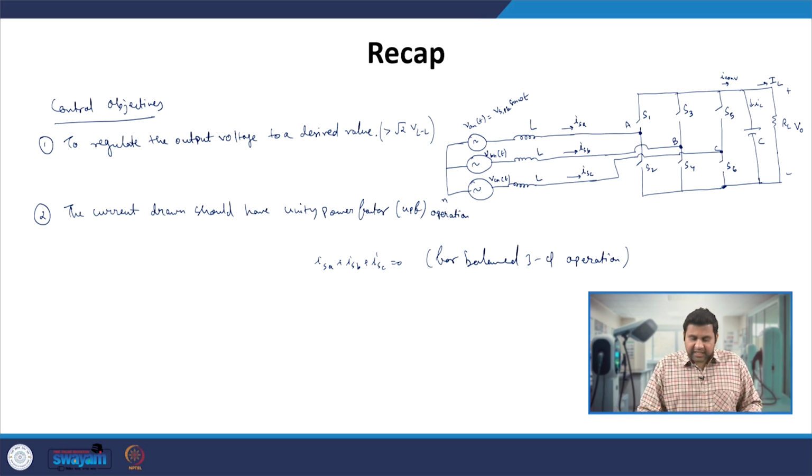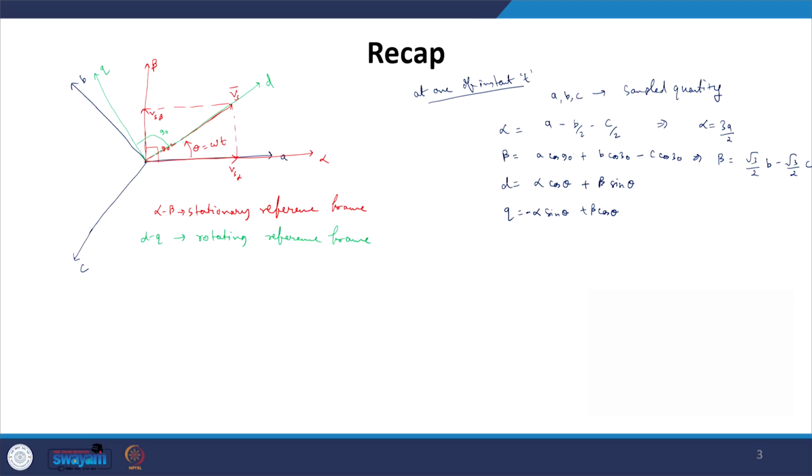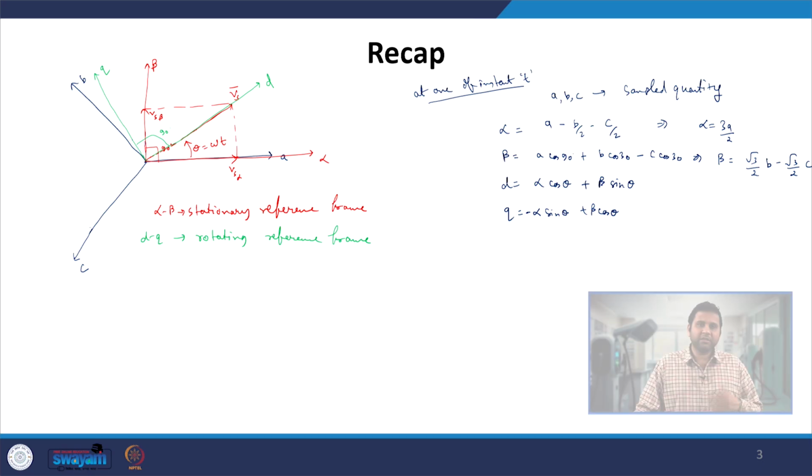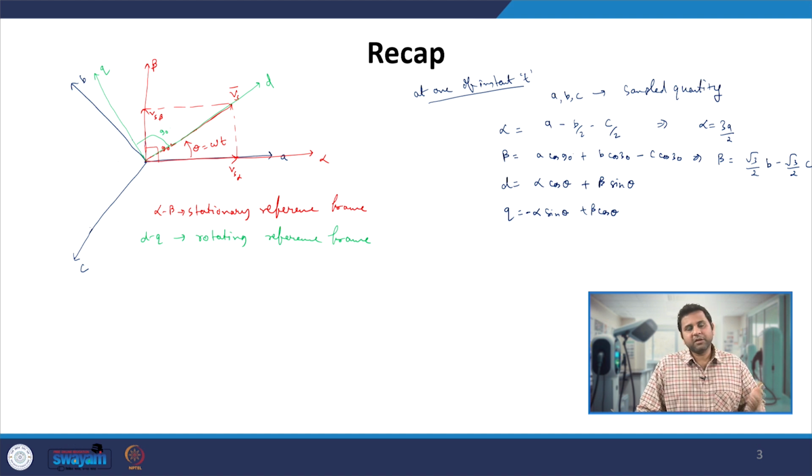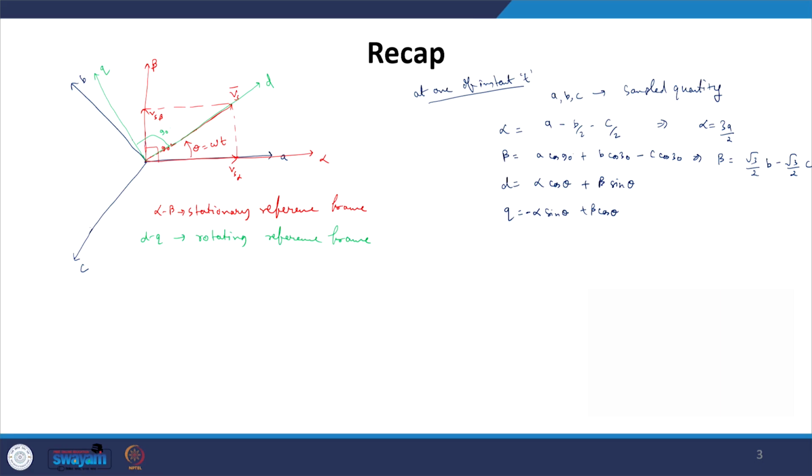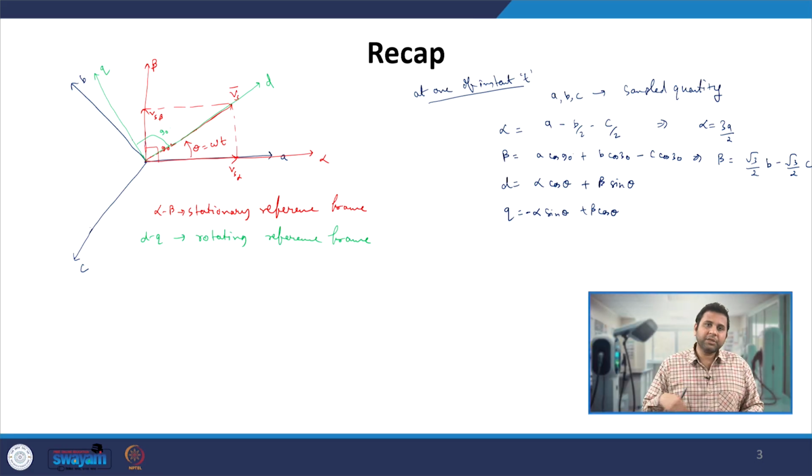So, that is why we need a mechanism by which we can make independent control of the currents in the 3 phases, and for that we have defined the space vector, which is nothing but a vector rotating in space with the same frequency as the frequency of variation of voltage with respect to time. This space vector is in the spatial domain, and the speed with which it rotates is the same as the speed with which voltage is changing over time t.